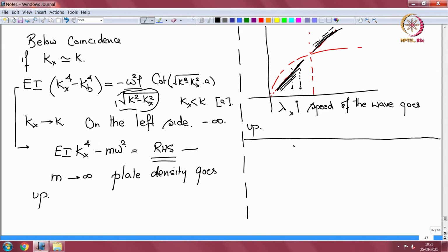This factor, the fluid loading parameter epsilon, is the coupling parameter between the structure and the fluid. If epsilon is set to 0 as we have seen, we get the uncoupled roots. So it's the ratio of the fluid density to the structural density.